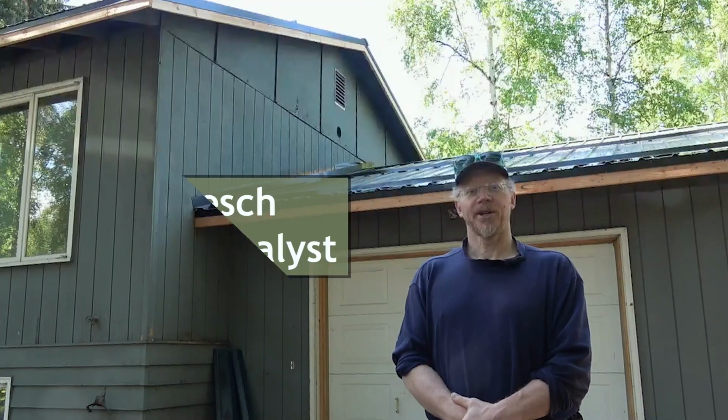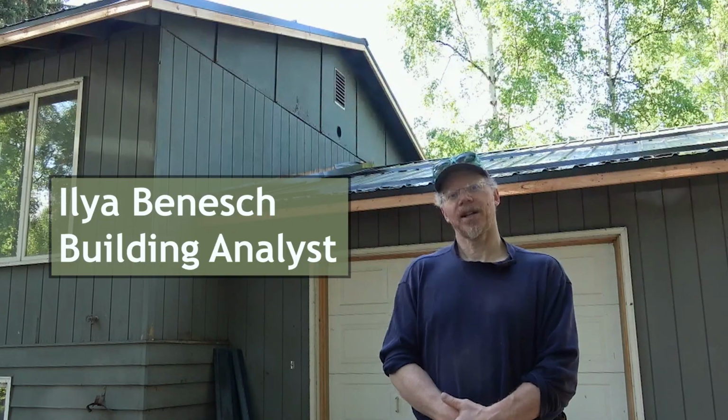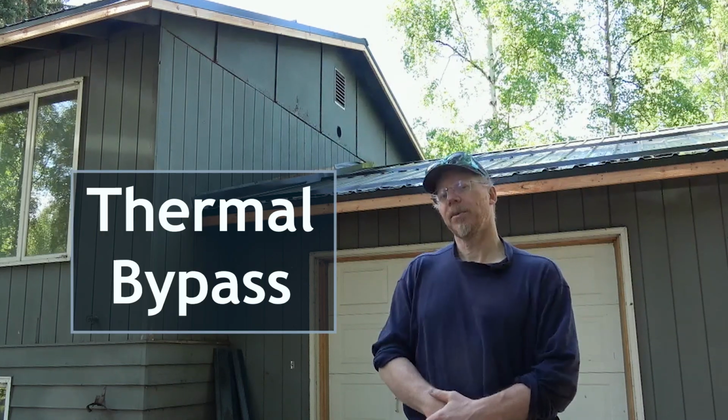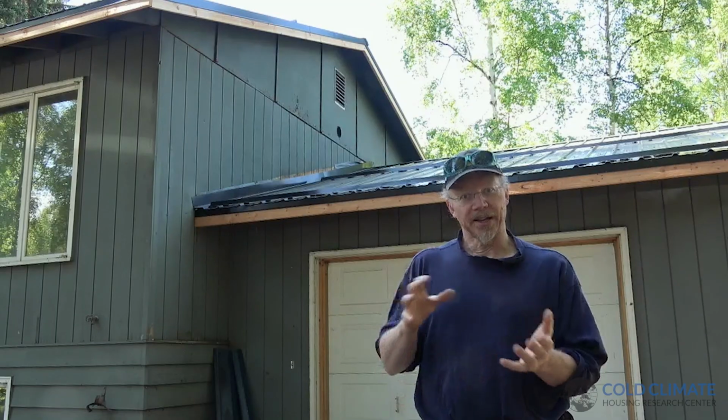My name is Ilya Benish, and I'm a building analyst for the Cold Climate Housing Research Center here in Fairbanks, Alaska, Climate Zone 8. And in this video, we've got a situation that we've finally been able to document, and the industry refers to this as a thermal bypass. Loosely defined, a thermal bypass is anywhere in our building thermal envelope where heat flows through or around insulation, essentially rendering it less effective.